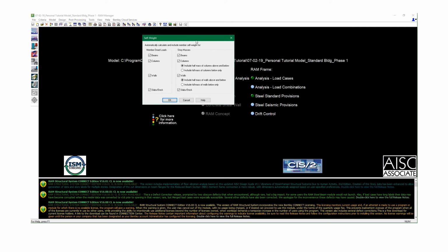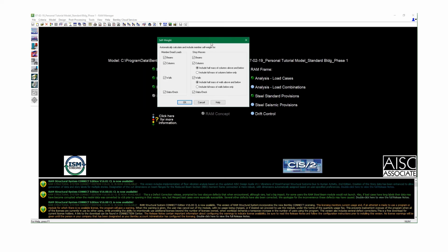The theory behind it is that for the frames, the lateral forces that are halfway between the first story and the ground are transferred directly to the ground, so no stress is seen or no forces are seen from the lateral frame resisting system in particular, from the first half of your story, if you will, or even the basement.